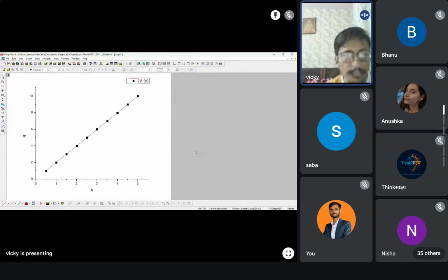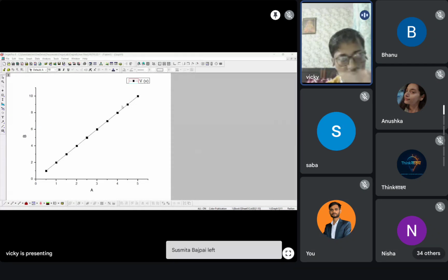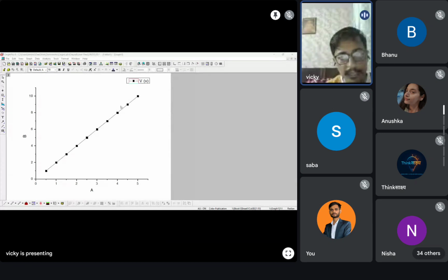Now, after plotting the graph, we have to customize it. For customizing, I have to select it. For example, you can click any number, like this part. After simply clicking, a screen pops up where we have a scale option, title format option, grid line, break, tick label, minor tick, customized tick label, and so on. So first of all, let's say I want to scale it. We have to change the scale.